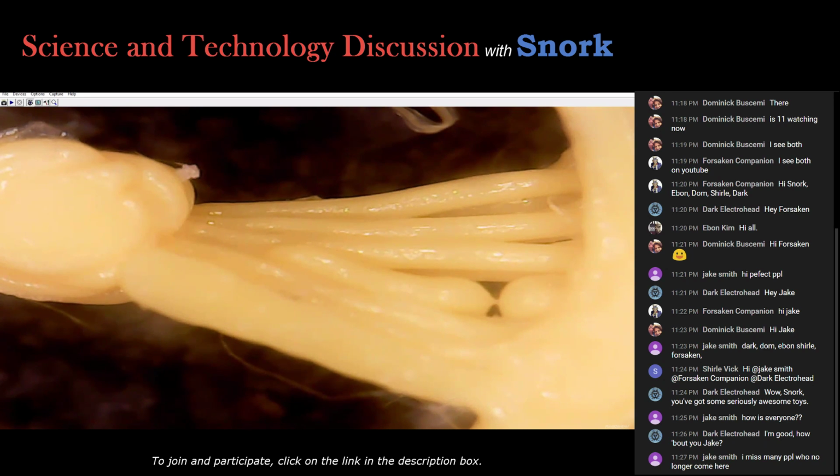For your windshield, as you can see here, as we get down into the microscopic part, there's ripple. Ripple in a windshield would mean fuzziness. And as you look at each of the 3D printing properties, you have to say, what can I tolerate? Well, sometimes brackets, anything cosmetic, usually can be 3D printed. I'm not saying always. I'm not saying that there aren't situations where you can't.